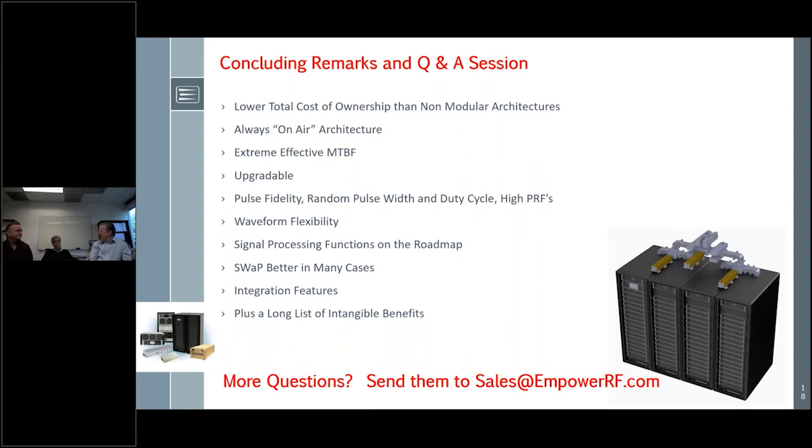Go ahead. For liquid cooling too. Yeah, for liquid cooling, it comes down to the shock absorbing, the damping, the planning for, even in one of those large cabinets, being able to have that. In one application that we have, it's in a tactical trailer that is a moving, relocating, open air range type of application, and it's definitely going to get bounced around out on the range, so we have planned for that from a mechanical perspective.